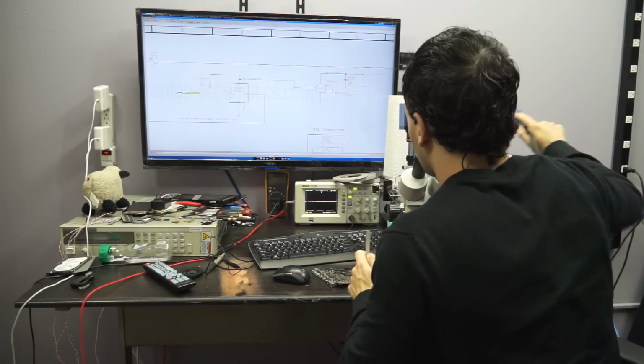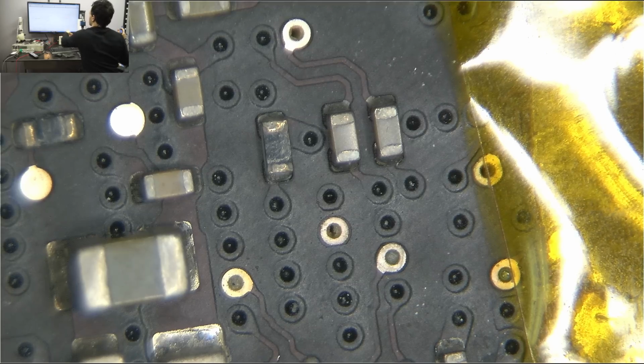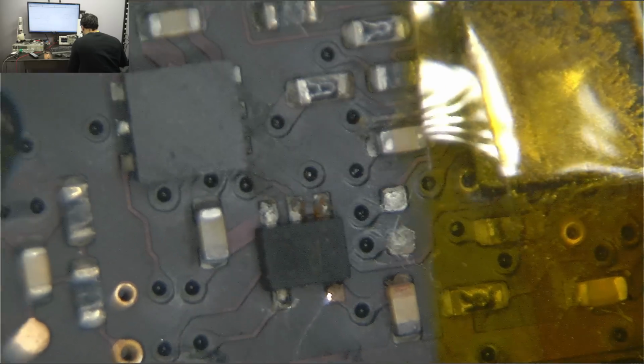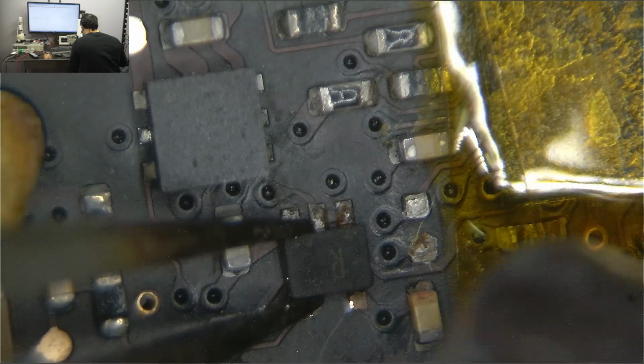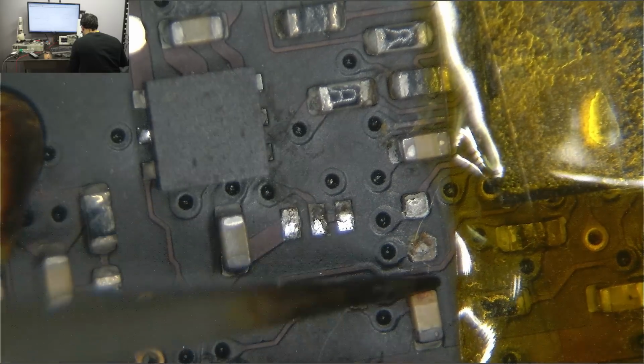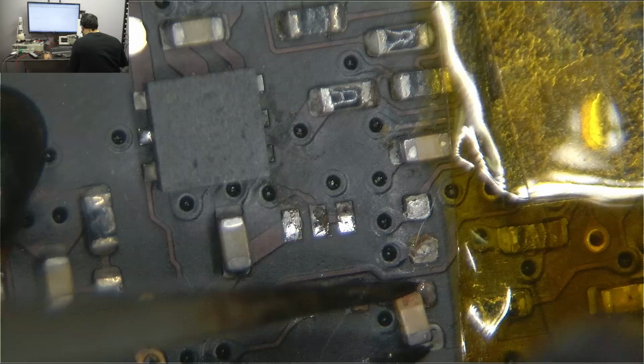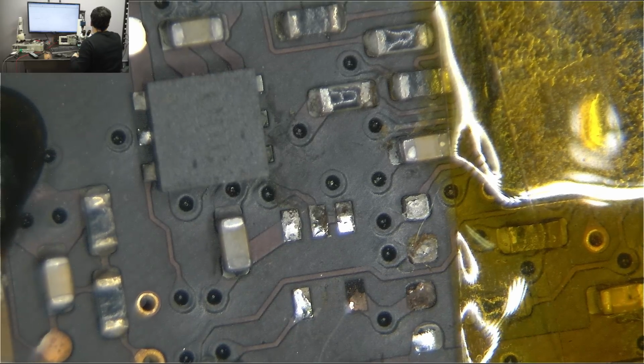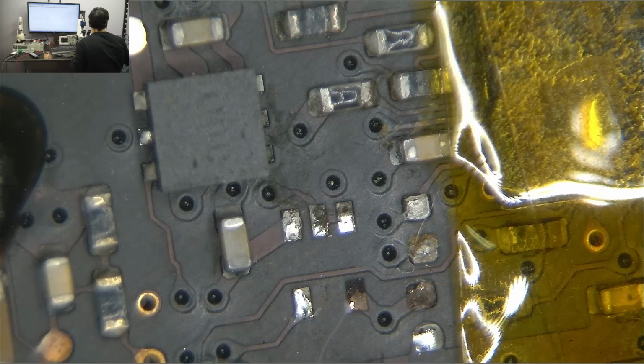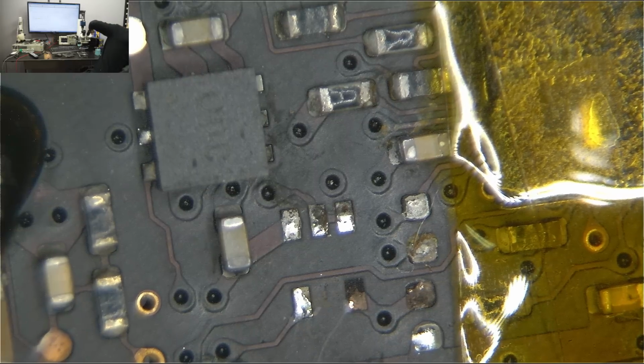So this is a bypass capacitor, C6908. That little bypass capacitor looks like crap. And also there is the actual U6901, which itself looks like crap, and that pad looks like crap. So I'm just going to take those off. And I don't even care if that logic gate was good. Honestly, I don't care. For all I know, that logic gate was good, and the only issue that I actually had here was that the pad on the board was just nasty. It really could have been an issue of the actual pad.